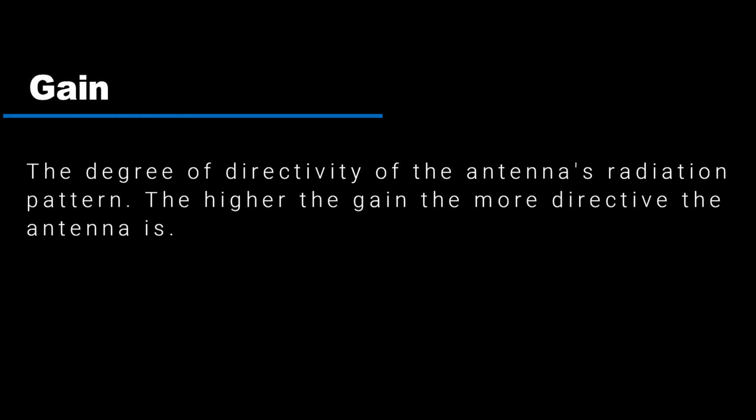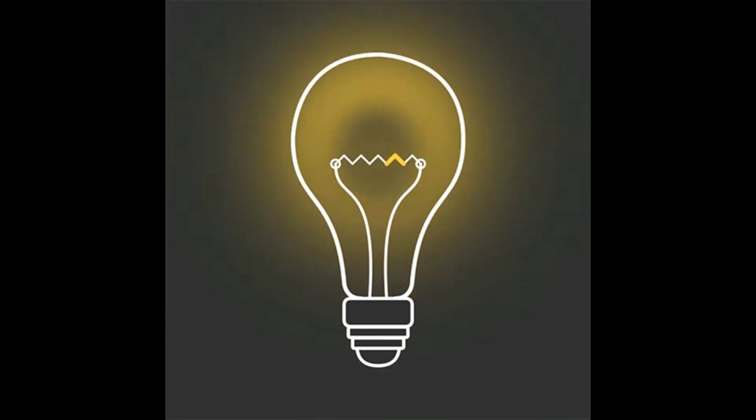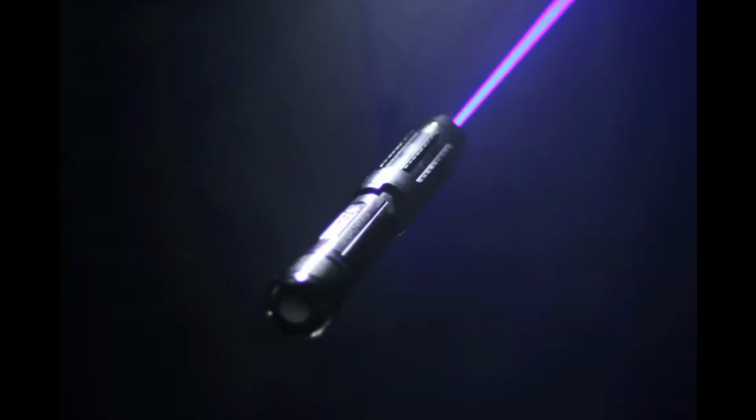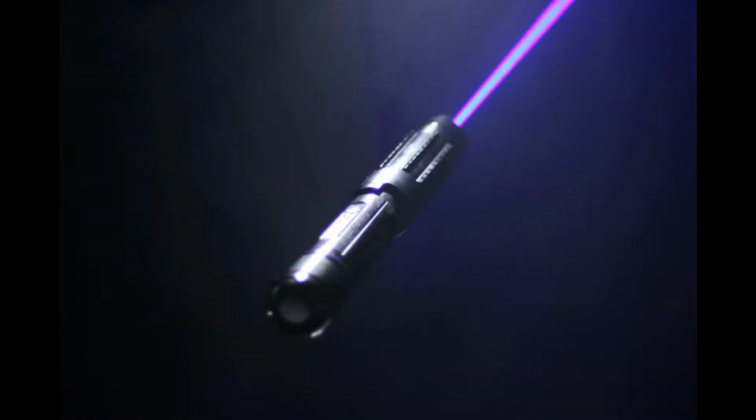Gain. Degree of directivity of the antenna radiation pattern. The higher the gain, the more directive the antenna is. Gain can be compared to light. A light bulb in a room radiates light isotropically, meaning it radiates in all directions. A laser pointer radiates its light in a certain direction. An antenna with a high gain is like the laser pointer in that it radiates its energy in a certain direction.